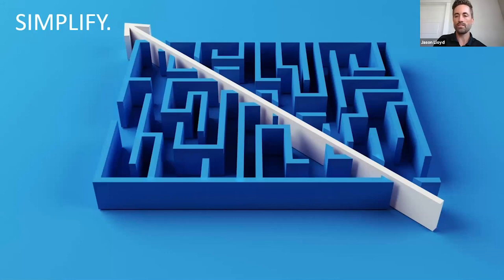They've already begun to do this actually in Wisconsin, for example, in which they've applied the guide specifications to many continuous twin tub bridges and have begun to develop simplified hand calculations that can be used instead for a bridge that meets certain criteria, including things like detailing, materials, fracture control, and certain geometry. Also, Texas Department of Transportation has recently added some simplified calculations to their bridge design manual for new twin tub girder bridges and system redundancy.